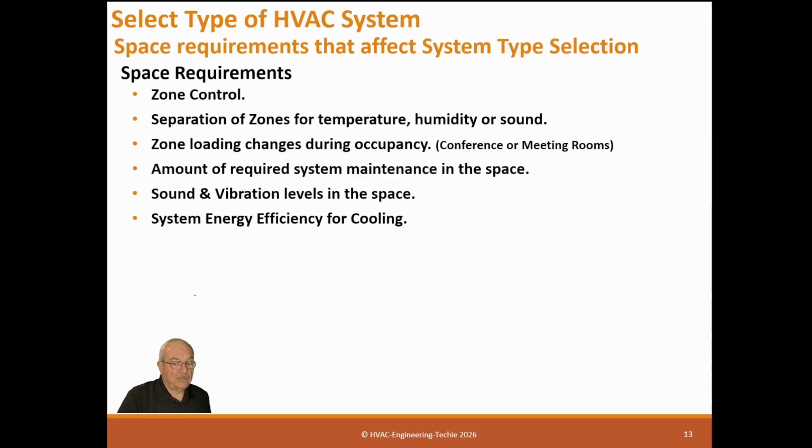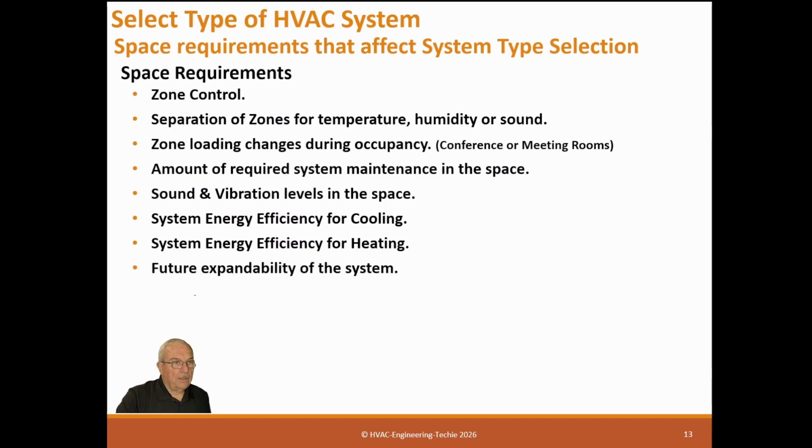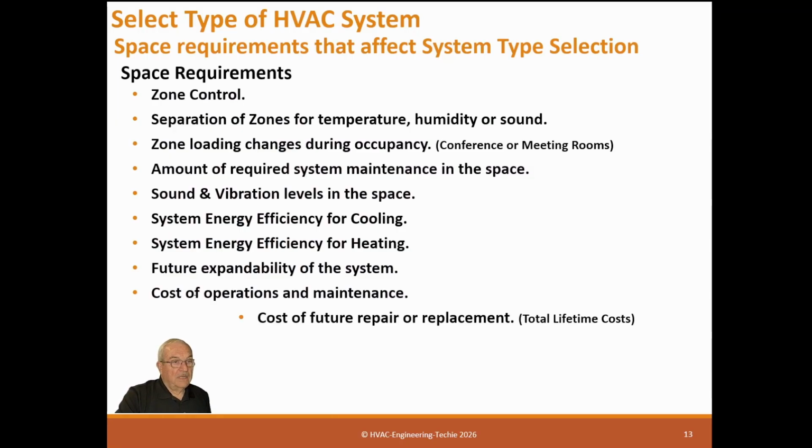System energy efficiency for cooling, system energy efficiency for heating, future expandability of the system. Can the system be expanded? Cost of operations and maintenance. How much does it cost to maintain this? Cost of future repair replacement, total lifetime cost. You can get a system now and say, oh, this is a really slick system going to work, but if it's got an issue that it cannot be repaired or it cannot be expanded later on, it could be a major disaster for an owner.